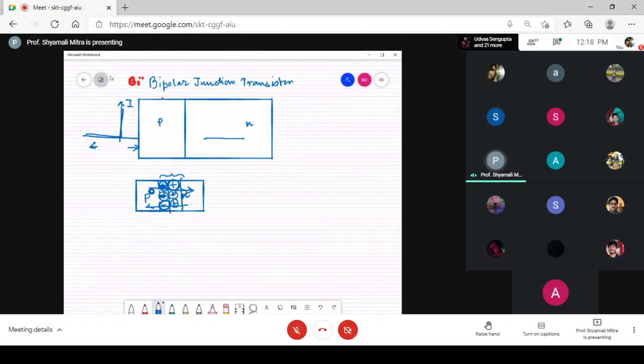So as and when it moves away from the space charge region towards the bulk region, more deeper into the semiconductor material, it has higher chances of recombination. So as a hole moves crossing the junction, by crossing this depletion region, it is expected that these minority carriers are lost with respect to the distance from this barrier space charge edge towards this edge of the bulk region.